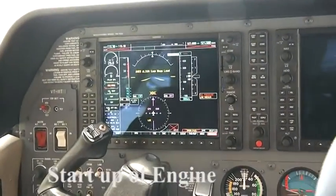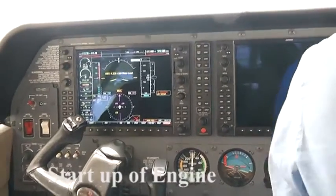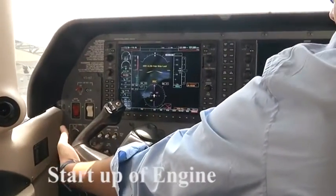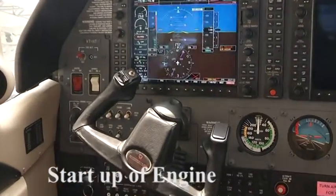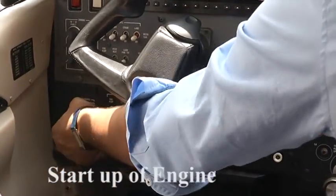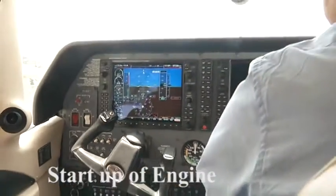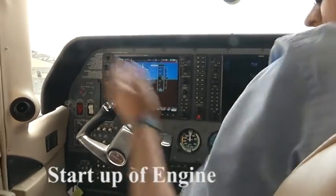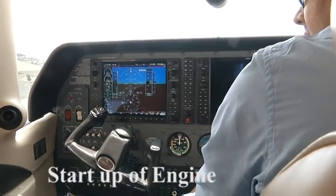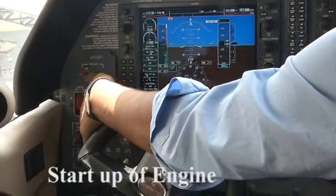Now mixture in, throttle half inch in, fuel pump on, then fuel pump off, mixture out, then crank ignition, right, left, both, then start. Now engine start. Now alternator on, avionics, beacon, nav, strobe.